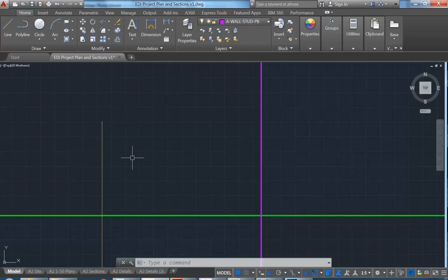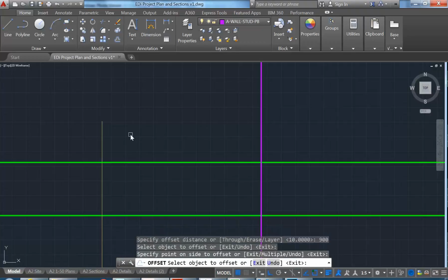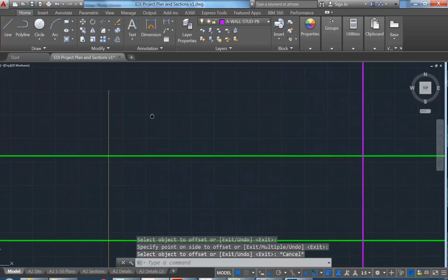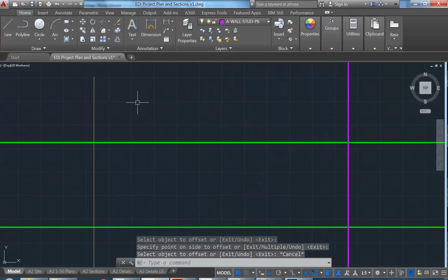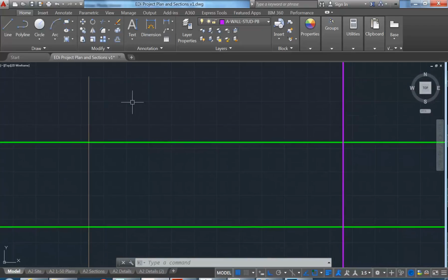What's the height for a kitchen bench? Roughly 90, exactly, 900 standard. There apparently is a movement of tall people trying to make it 950, which is ridiculous. I get a sore back when I'm working in those kitchens, and other people, because they're not as tall, have often tried to make them lower than that.